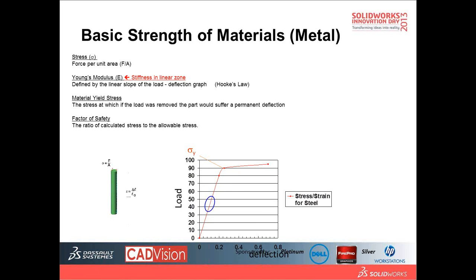What linear analysis tells us is, will the part yield or not? So usually in design, we try to design things before yield. But some places might not necessarily have this constraint, because after yield the part is still very able to be used during product usage, right? So it's very important to investigate what happens after yield and compare with your linear static result.